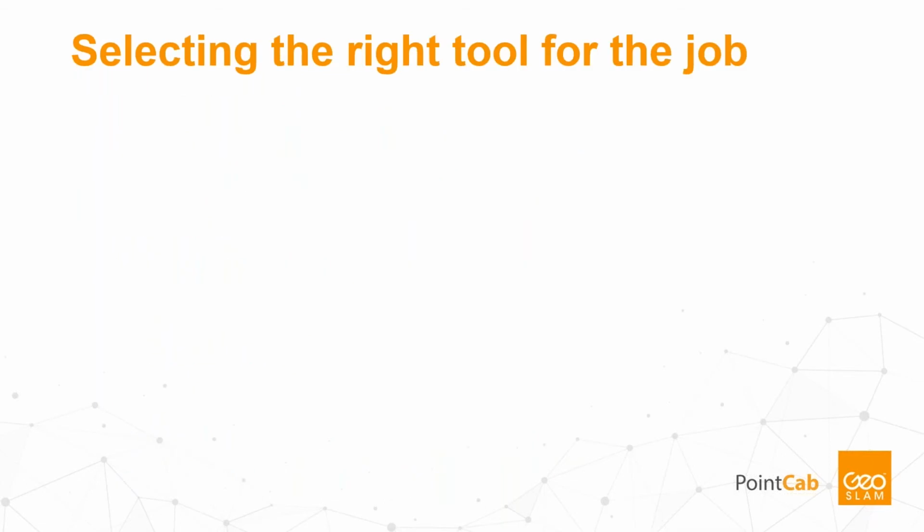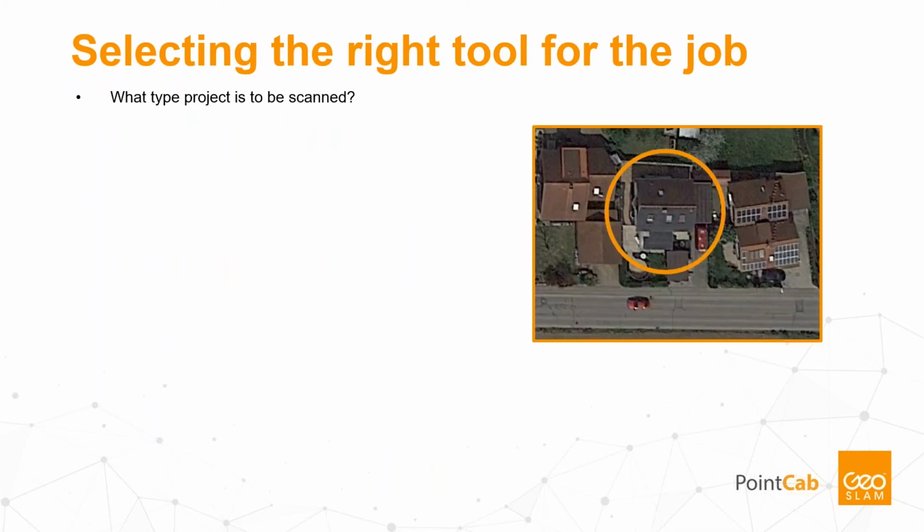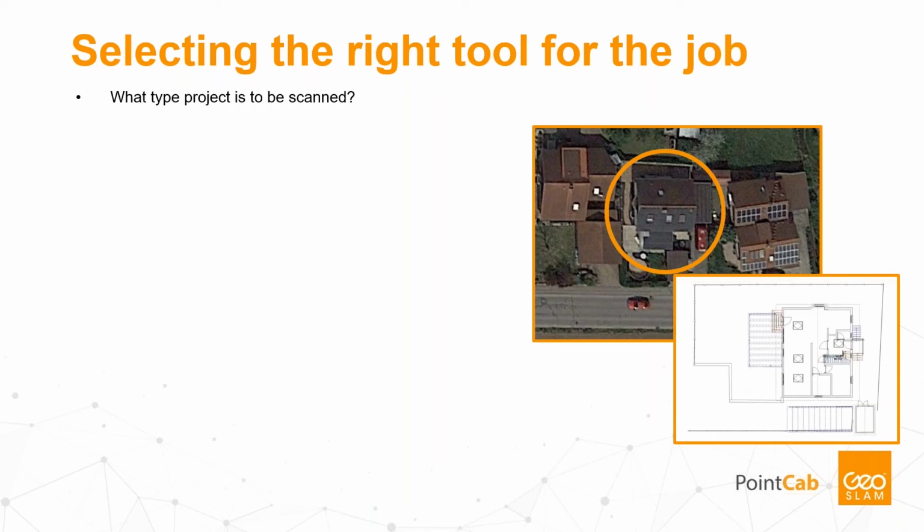So to start with, selecting the right tool for the job. What type of project is to be scanned? In this case, we had a house that needed to be scanned inside and outside as well. The house has 3 floors, and we were provided with a drawing in advance, which is a common application for the measured building survey to find out what a true building is compared to its design.